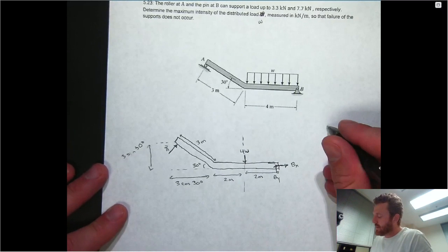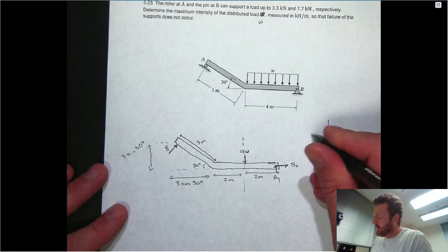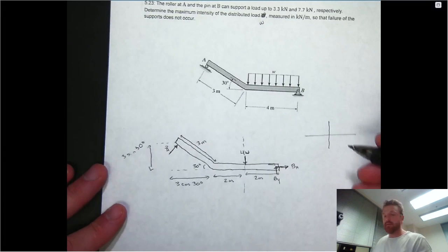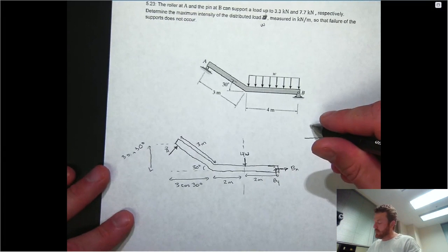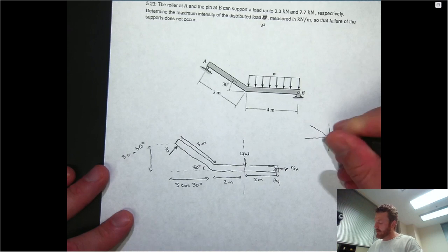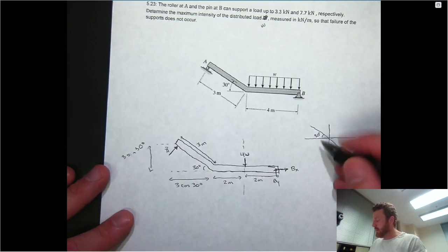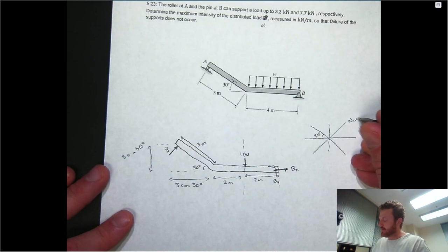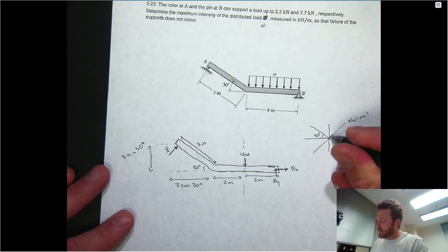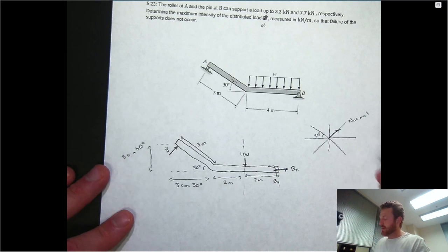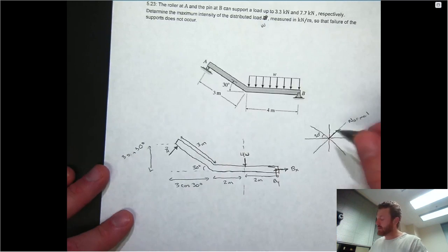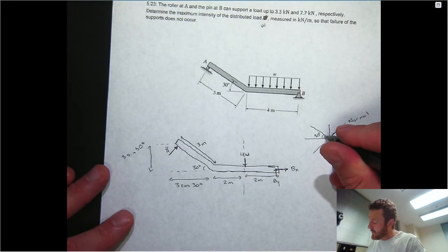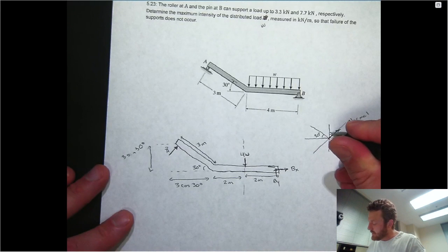The only thing we need to do, just in case it's not obvious to anyone, if I had a standard XY coordinate system, if I lift the horizontal side by 30 degrees, which is what they did when they created this bend in the beam, that will effectively shift the vertical by 30 degrees as well. So this is the normal axis. This is the direction along which that force of the roller, the reaction, acts. So if this axis shifted by 30 degrees, this shifted by 30 degrees as well.